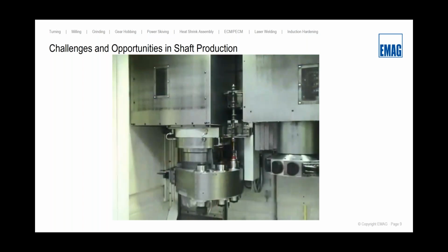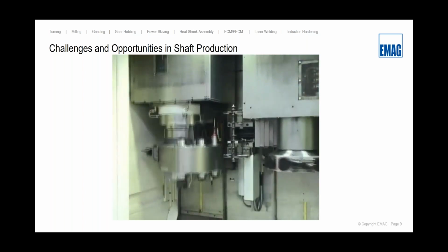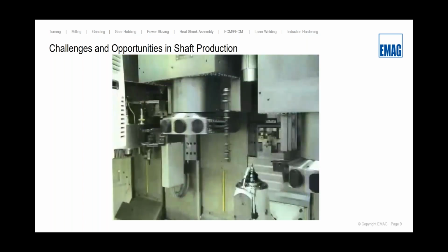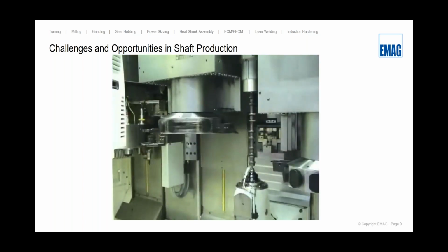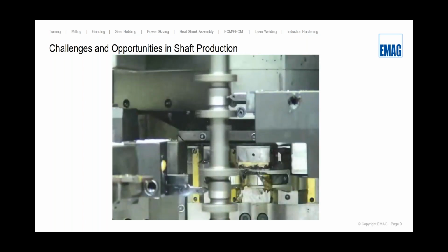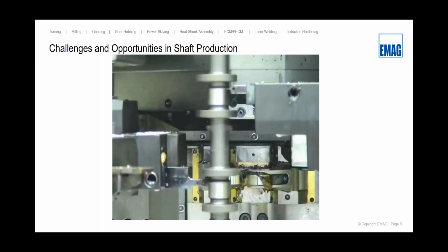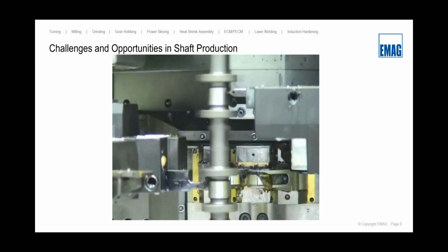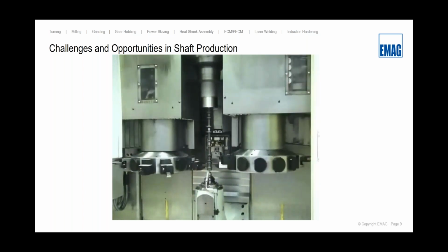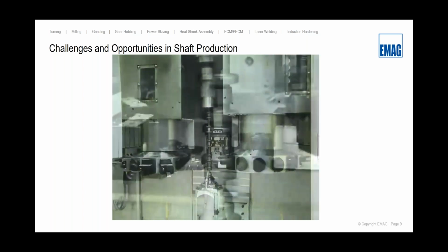So what you're going to see next is the middle turret. I have 3 turrets in the machine. It's going to transfer the part to the next station. Now, video is not harmonized perfectly, but all these operations are happening quite seamlessly. So now that I've transferred the part to my second station, now I'm doing my 4-axis turning. I've got a 3-jaw chuck. Maybe sometimes I'm using retractable jaws.